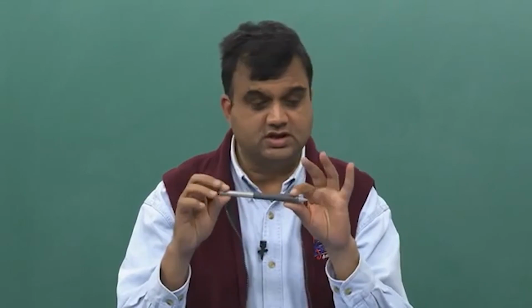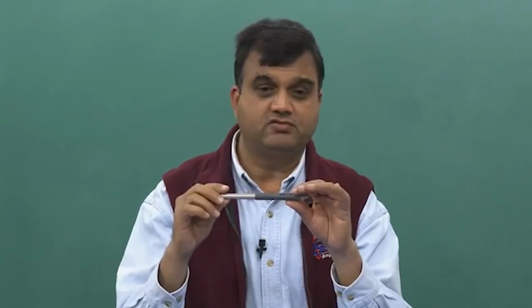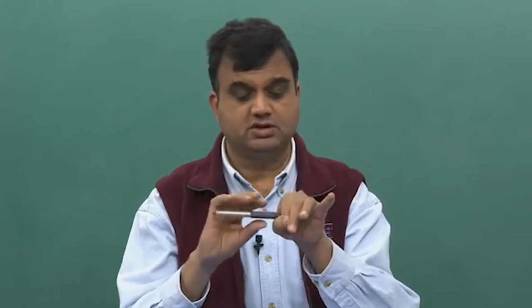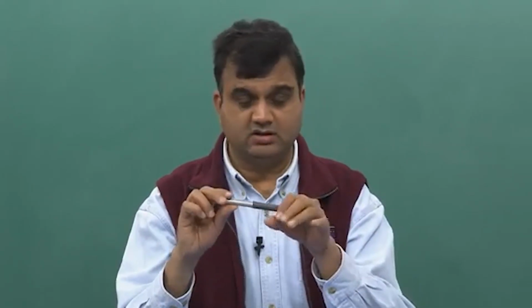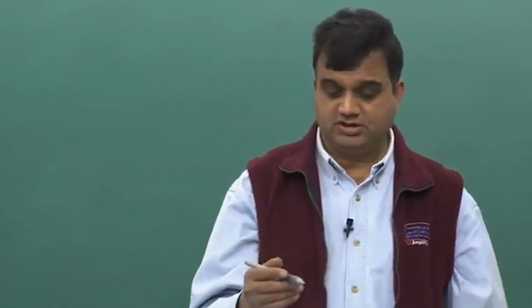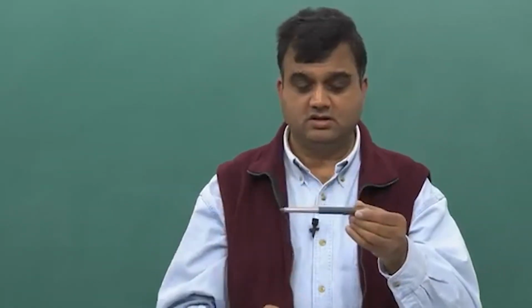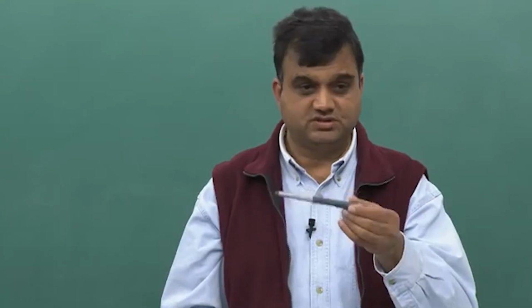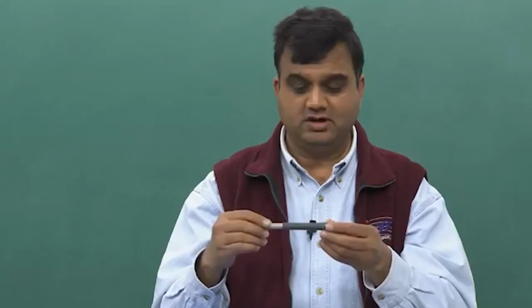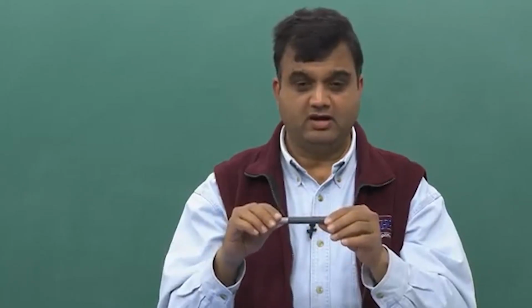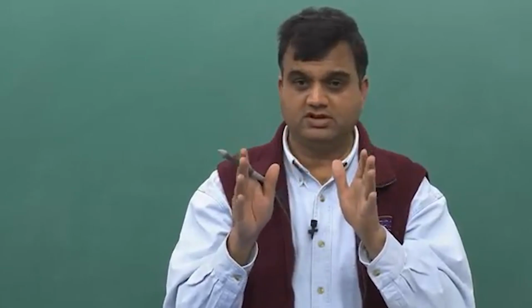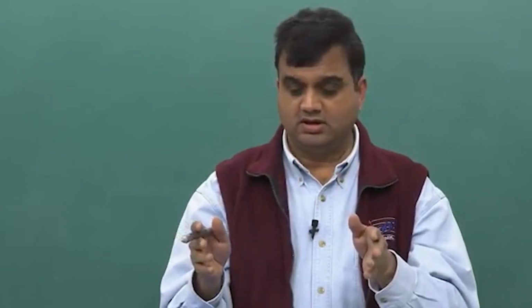For instance, in the case of the beam, what is it that we are trying to do? We are applying a force, and as a consequence of this force, this structure is bending. So, what I am trying to develop is a set of equilibrium equations, because there is mass here, there is stiffness, there are forces, and Newton's laws tell us that this thing will bend and move only if the external forces on each small element of this material are not 0.